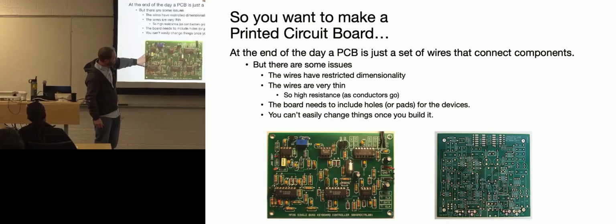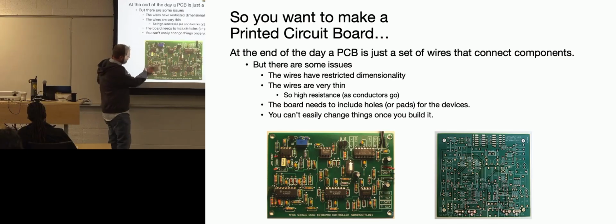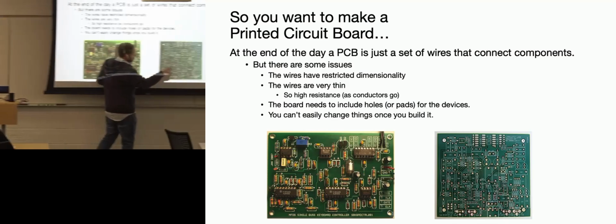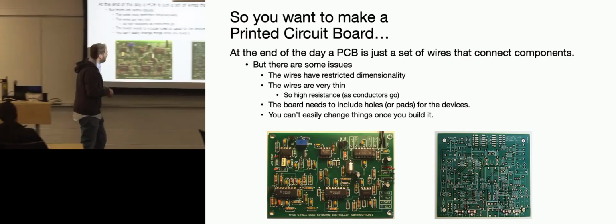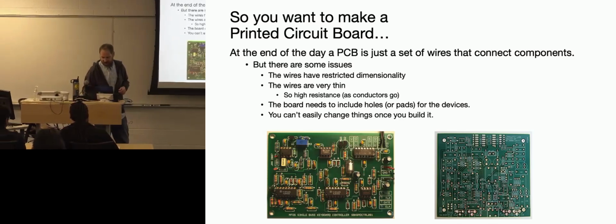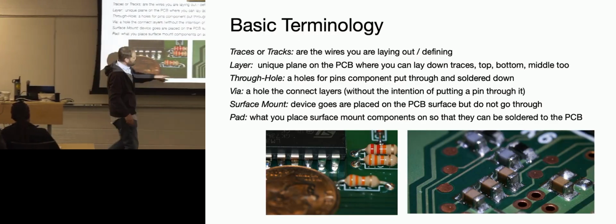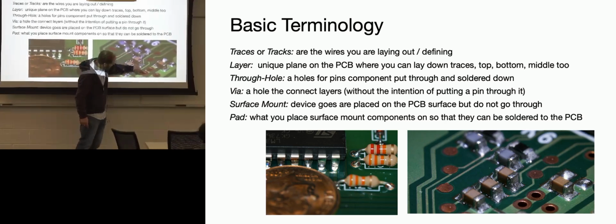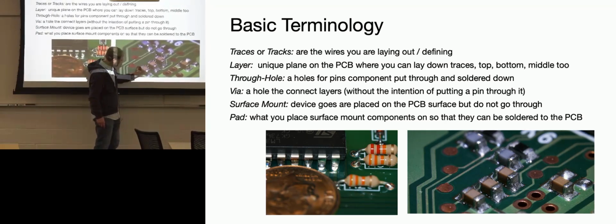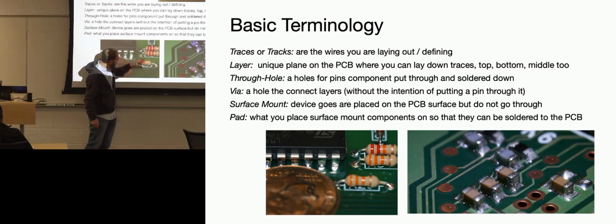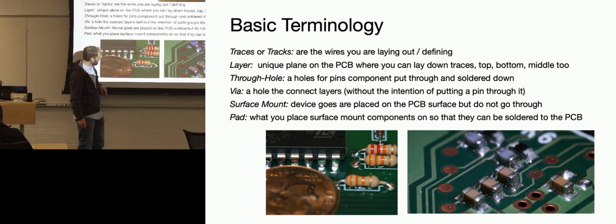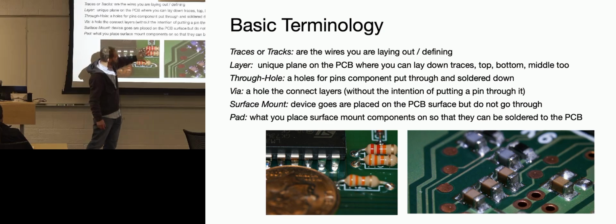And so here's an example. This is a through-hole board, which is becoming more rare here, where, once you make the PCBs, the parts are placed through the board. The more common type is a surface mount, which looks like this. You don't have the hole that goes through. You have a part that sits right on top. And this is nice because with the through-hole, the hole goes all the way through, and I can't put things underneath it. So this actually eats up a significant amount of space over time, making layout harder, although it is a much cheaper way to make PCBs.